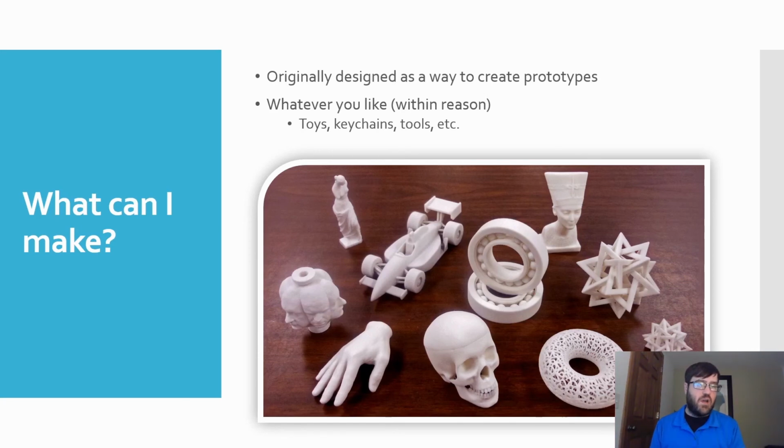And the last thing there, sorry, I went a little bit quick, was the polyurethane. Polyurethane can be used to waterproof or water seal a print when it's finished, but you should only be using polyurethane on prints made out of ABS, not PLA. ABS is a much stronger material and can hold up to, you know, being coated with polyurethane. PLA prints, not so much. Again, only if you're trying to water seal, like create a vase or something.